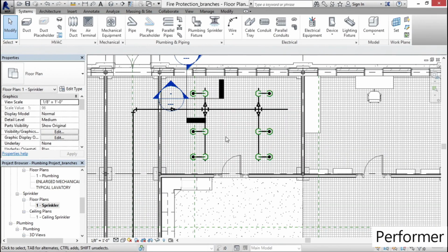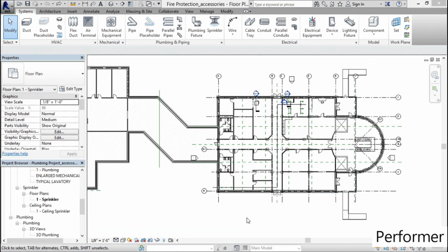As I may have mentioned before, not every ceiling will be this low. Just like we did, I like to over-exaggerate the room that I need, then go back and cut a section, making sure I am fitting in my allotted space. As you can see, it can be tedious, but by the time you're done, you're going to have 3D views, plan views, and systems. We'll need to make some modifications to the valve so Revit doesn't add any reducing fittings.